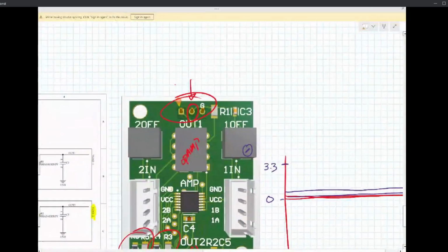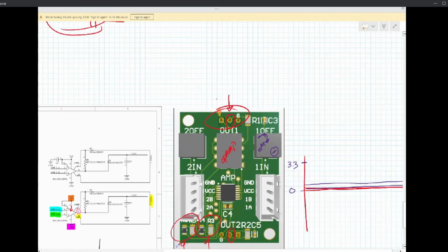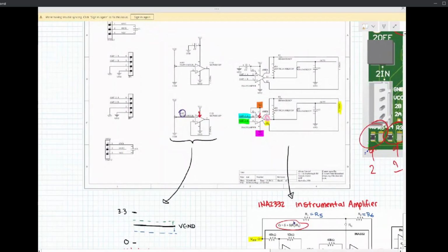Actually, one thing to know about that is most of the strain gauge PCBs that we have right now, most of the amplifier PCBs, don't have this trimmer pot in, because the one that we got was really bad. So we just have 2 resistors going like here and like here. You can also play around with those, but that is for setting your virtual ground.